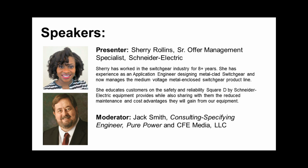And really, there are two means of grounding typically used in the United States for withdrawable equipment. One that Sherry mentioned was a ground and test device. This is a removable element, like the circuit breaker is removable from the switchgear, and you insert this grounding device, and it's a means to connect between the cable side or the main bus bar side of the switchgear to the ground.